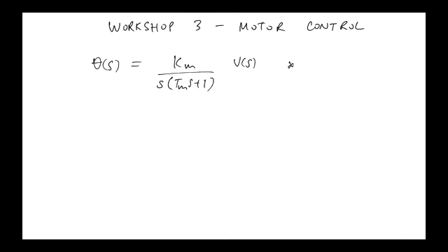You're identifying the parameters in a model, but you're doing it by hand, by simulation, until the simulated response matches the observed response. The voltages applied were ramp type signals, and you saw the angle would follow the ramp and then turn around and follow. How it turns around has to do with the time constant Tm, and the slope of the line is related to the gain Km.